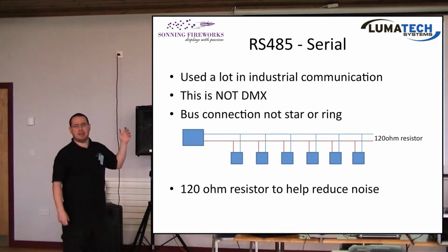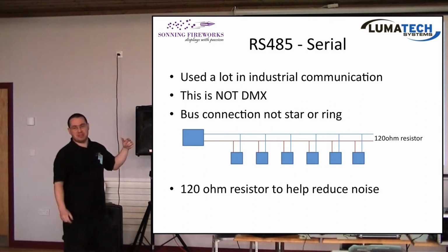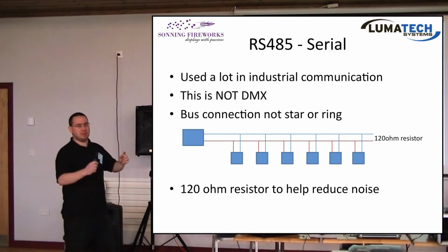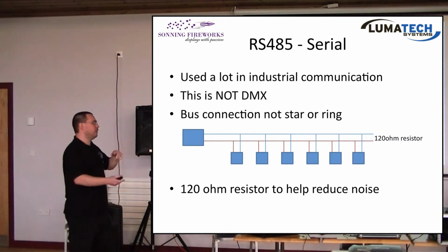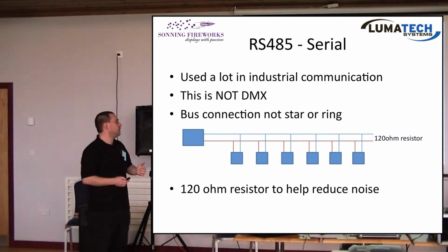If you've ever done any intelligent lighting, like disco or theatre, this is not DMX. DMX is a higher level protocol. If you've ever been to a concert with all the fancy lights, that's controlled by a protocol called DMX, which runs on RS-485. But the firing system technologies do not use DMX because it's got no error correction, no error detection and that kind of thing. So people often think that RS-485 is DMX and vice versa, but they're different levels in that protocol stack that we were talking about.